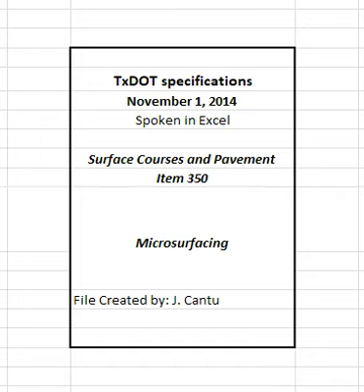4.9 Curing. Protect the finished mat from traffic until the mixture cures and will not be damaged by traffic. Adjust mixture properties according to humidity conditions and ambient temperatures to allow traffic on completed travel lanes within 1 HR after placement with no damage to the surface. Protect locations subject to sharp turning, stopping, and starting traffic for longer periods when necessary.